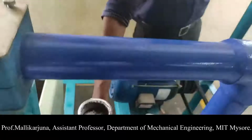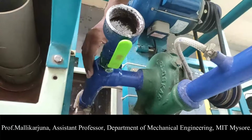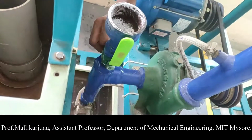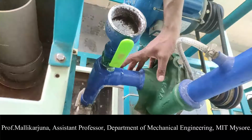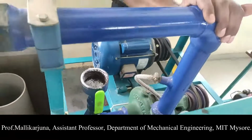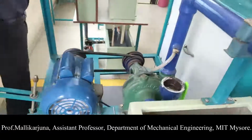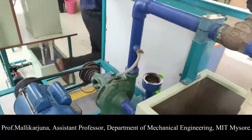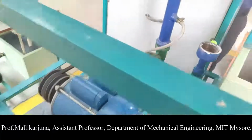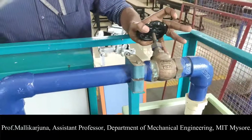Now if we look at the various other pipelines we have here, this one is the suction pipeline from the sump. This pipeline is going to suck the water from the sump. Then this sucked water will be energized and pumped through the delivery pipeline. So this is the delivery pipeline we have. In order to adjust the delivery, we need to operate this valve. So this is in the completely closed position now.